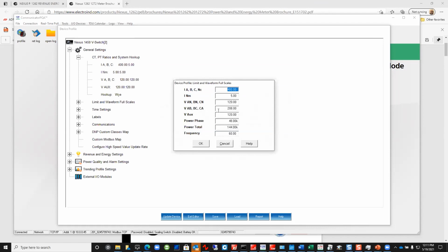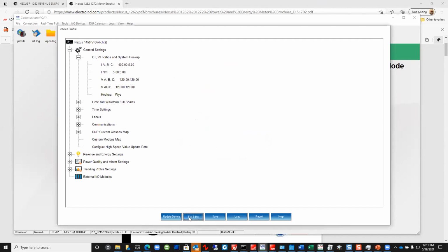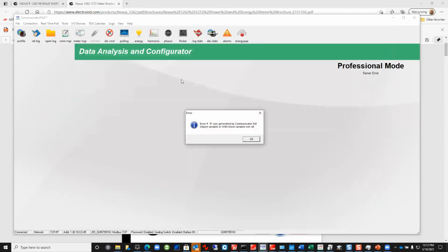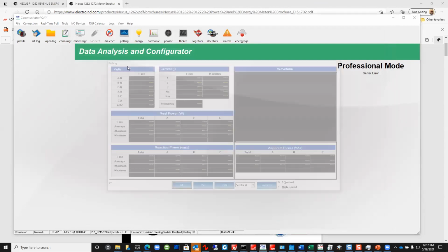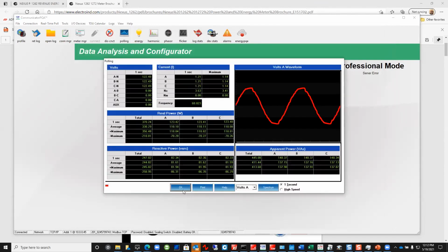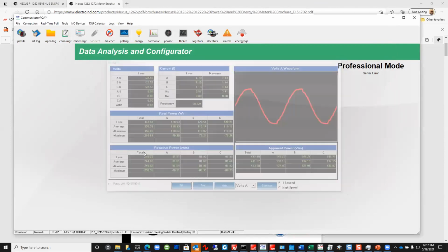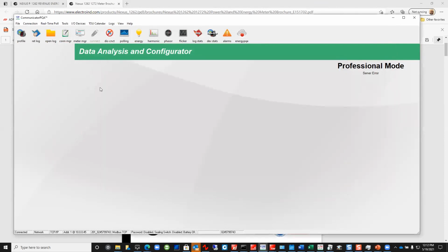So here's our calculation, just like we saw in the other case, based on what we chose, 400 to 5. In this case, as I mentioned before, I think I took a quick peek at my load. It was like 1.19 amps. And I'll just take a quick look again. We'll just exit here for a second to confirm. So just to see, 1.16 amps is really what I want to set my limits eventually.